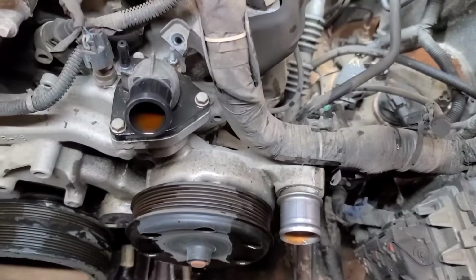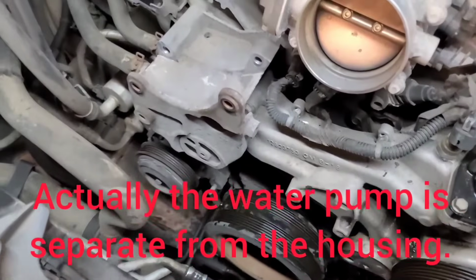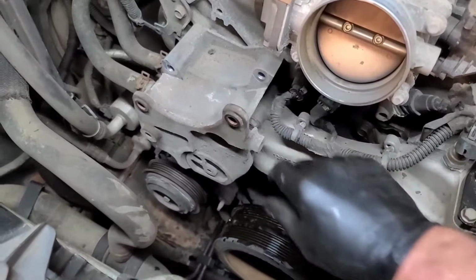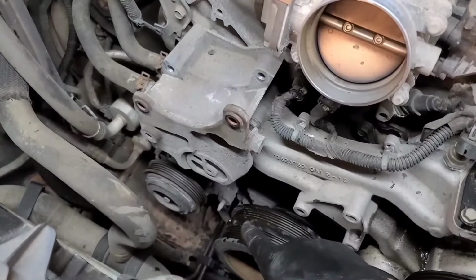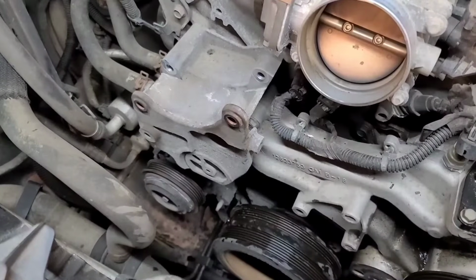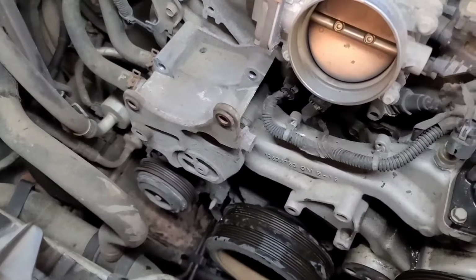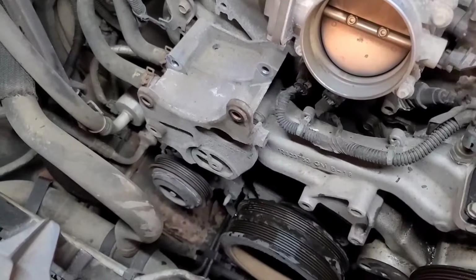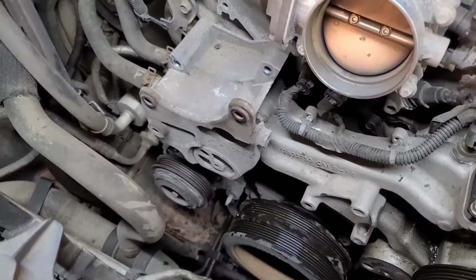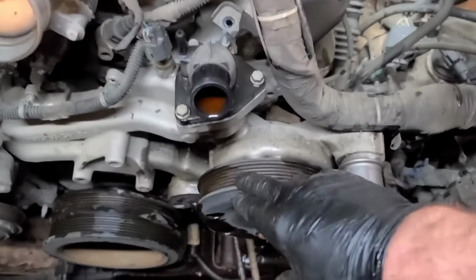Boy, they sure made this water pump a pain to change now. I still haven't figured out exactly what we have to do with that AC bracket, because this bracket that holds the alternator on goes behind the AC compressor down there, and it's over top of the water pump, so all of that has to come off to do a water pump. I can't imagine what it used to be, quite simple. 4 bolts, didn't have to touch anything. It was easy to do a water pump. Now they've complicated it. This obviously is the water pump now.